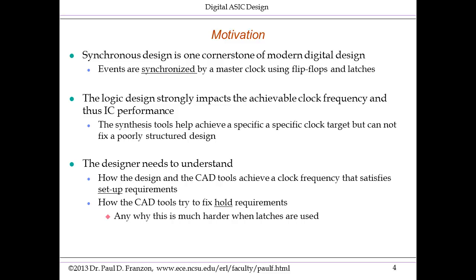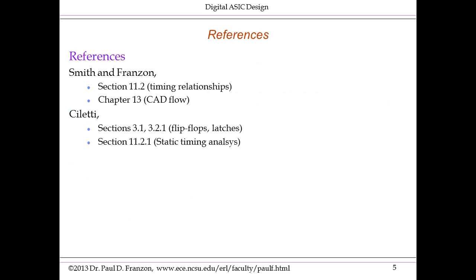In addition, much of the CAD flow is related to managing timing, usually to achieve a specific clock frequency. These are often referred to as setup requirements. And you have to learn how to manipulate the CAD tools to meet setup requirements. In addition, you have to meet what we'll describe as hold requirements. We'll come back to this in the next submodule. But here, later in this module, you'll see why I recommend flip-flops only, because it's very hard to meet hold requirements with latches. Here are the references for this particular module.